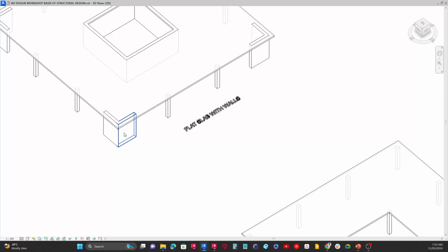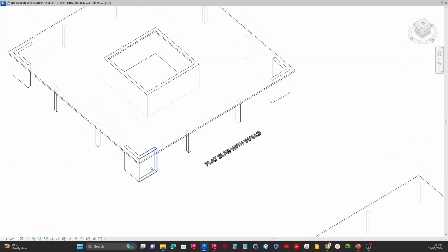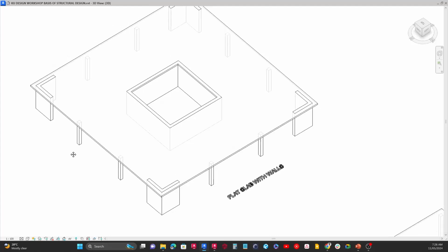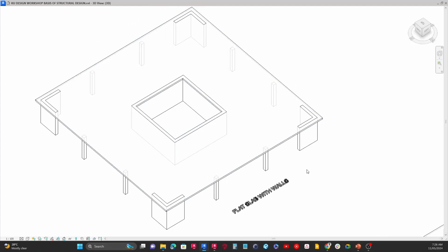Sorry, the walls may cause some sort of obstruction, so you're only going to be placing walls in areas where they're not going to cause obstruction. Another advantage of having walls is that they can form a core for the building, which can help it resist lateral loadings, such as wind and seismic forces that may cause the structure to sway and collapse. So that's the reason why we have these walls. Most of the time designers prefer to place them at the center to make the core of the building a little bit stronger, and that's where you see all those elevators, shafts and staircases.